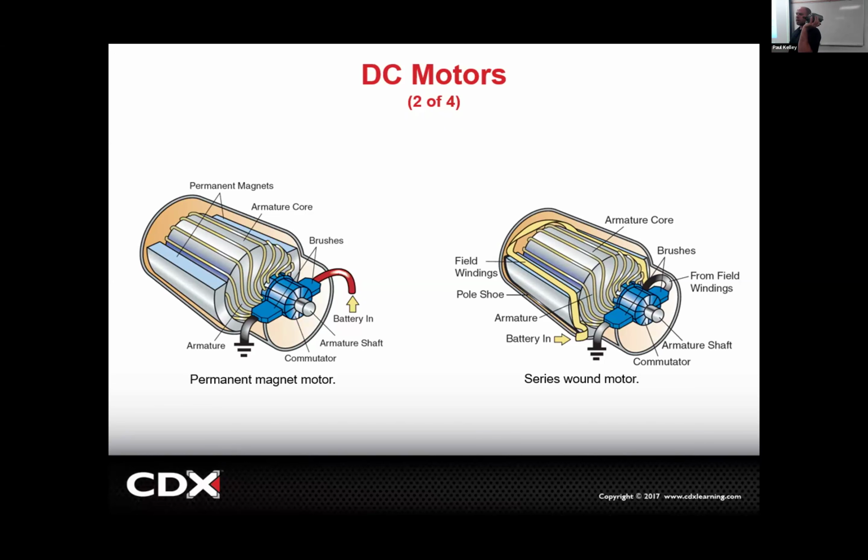Same thing if it was a fuel pump. I mean, I've even done this. If I go out in the dealership and go to start the vehicle and it's a crank, no start, I listen, I hear no fuel pump, I think the fuel pump is bad. I've been known to sometimes roll under the vehicle and punch the fuel tank, pow, and get back in.